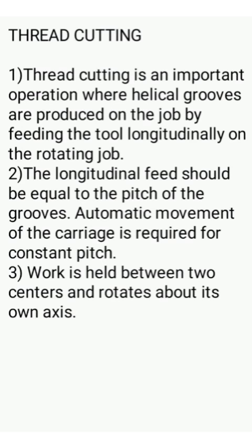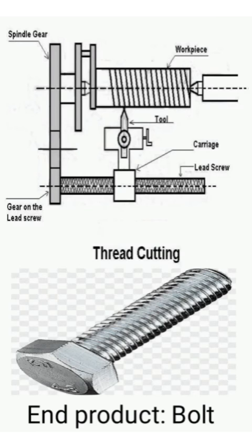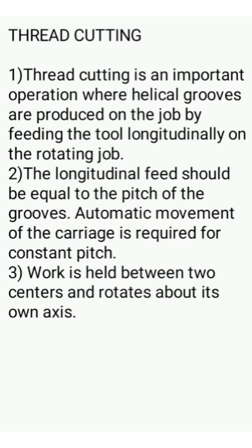Thread cutting. Thread cutting is an important operation where helical grooves are produced on the job by feeding the tool longitudinally on the rotating job. The longitudinal feed should be equal to the pitch of the groove. Automatic movement of the carriage is required for constant pitch. Work is held between two centers and rotates about its own axis.